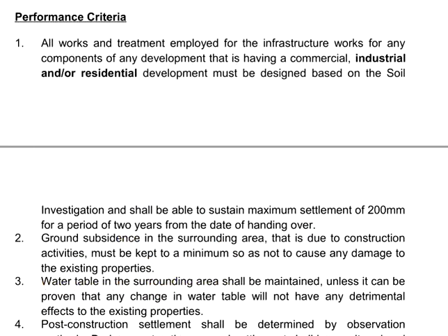Let us talk about the performance criteria for the development. It's stated that all work and treatment employed for the infrastructure work, which refers to the roads and drains, must be designed based on the soil investigations, and should be able to sustain maximum settlement of 200 mm for a period of 2 years from the date of handing over.